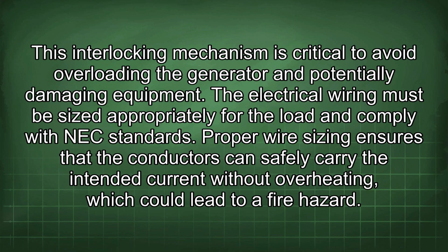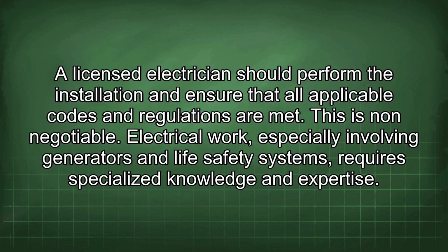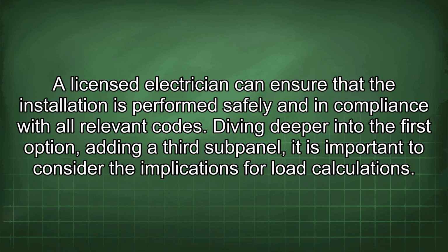The electrical wiring must be sized appropriately for the load and comply with NEC standards. Proper wire sizing ensures that the conductors can safely carry the intended current without overheating, which could lead to a fire hazard. A licensed electrician should perform the installation and ensure that all applicable codes and regulations are met. This is non-negotiable. Electrical work, especially involving generators and life safety systems, requires specialized knowledge and expertise. A licensed electrician can ensure that the installation is performed safely and in compliance with all relevant codes.